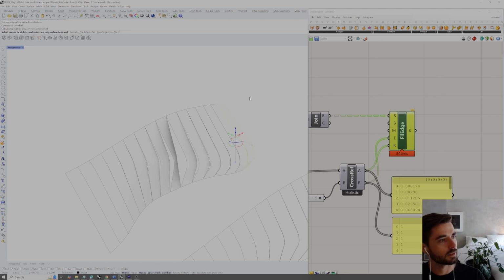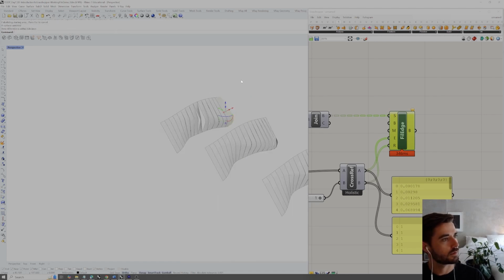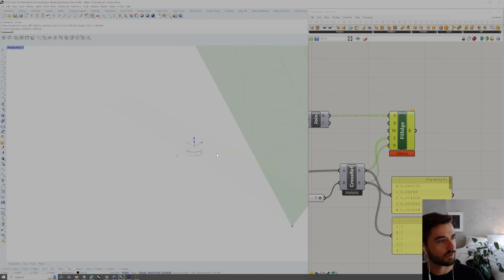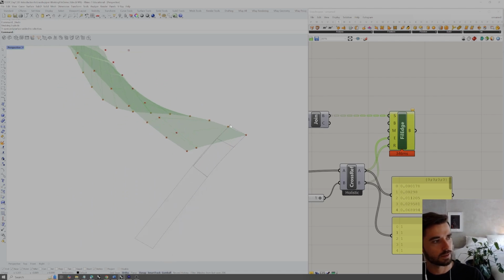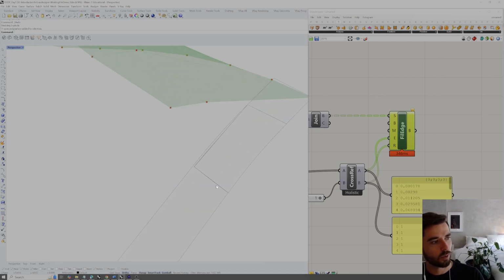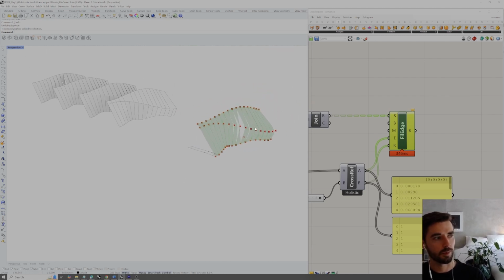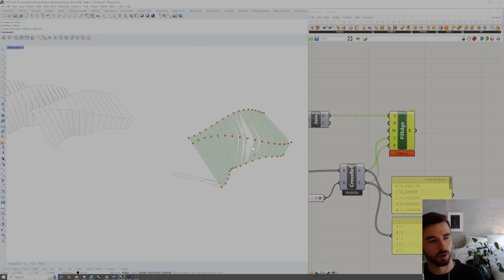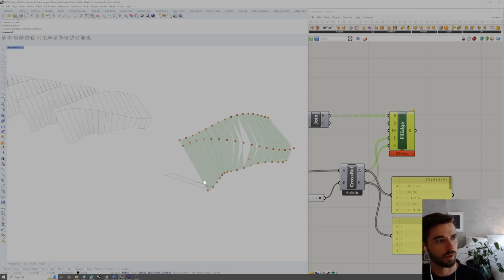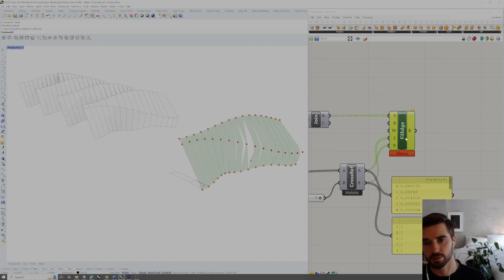So if we select one and type Unroll Surface, we can see these surface panels unrolled. And with them joined, all you have to do is cut the outer profile, and you could score these 2 lines on the inner radii, and that would allow you to bend this strip to form this parametric fin wall condition. So that's all for this bonus video. I just wanted to show this as an alternative to the workflow that we went through using Surface Box Morph.